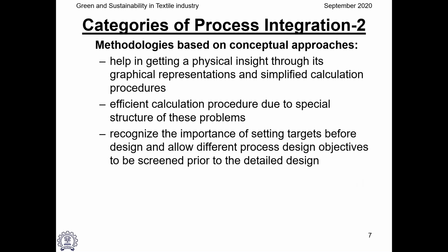Then there is one other important thing, which is setting a target before actually solving it. It doesn't say what exactly will be the solution of the problem, but it will simply say this is the objective function, and it can be done very efficiently. And that's the way it is extremely helpful for industry. They know where to stop. So suppose the target is 100 and you have reached up to 95, you know there is no point in putting too much effort or time, and you can go ahead with that 95. Maybe next time you can improve further. But if you are at 75, you know that you are too far away, and you should look for the actual solution. So that way it helps the industry, and that's why the industry has taken up pinch analysis in a big way.